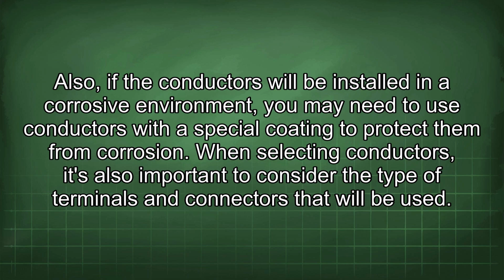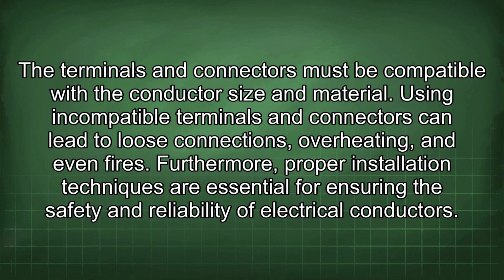When selecting conductors, it's also important to consider the type of terminals and connectors that will be used. The terminals and connectors must be compatible with the conductor size and material. Using incompatible terminals and connectors can lead to loose connections, overheating, and even fires.